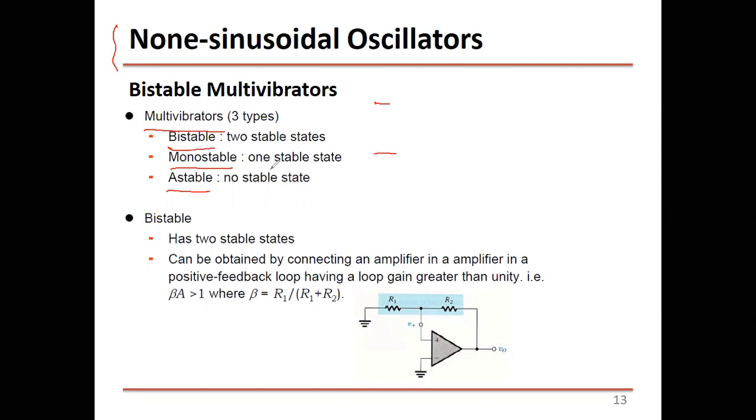As I mentioned before, like the doorbell button, all the time it is in the 0 state, right? Once you press it and release it, it's going to go momentarily to the on state and then go back to the off state again. So this is what we call monostable. It just has one stable state, and it can go to the other state for a short period of time and then comes back to the stable state. But this one you can switch to either one of these two states, either high or low. So this is why we call it bistable.